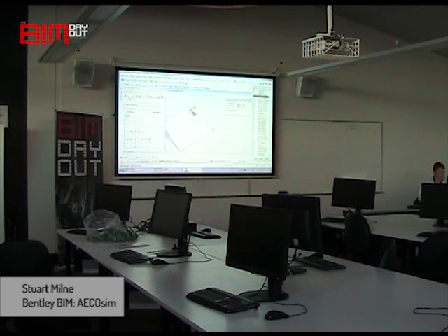The way you can check that is you can hold down the Shift key, hold down your mouse button, and rotate around and have a look. It should be on exactly the same angle. You will just place out this first point.